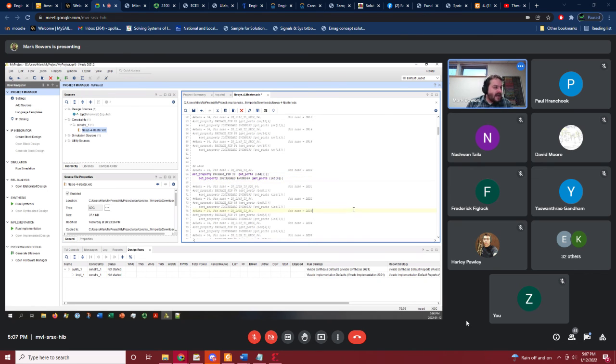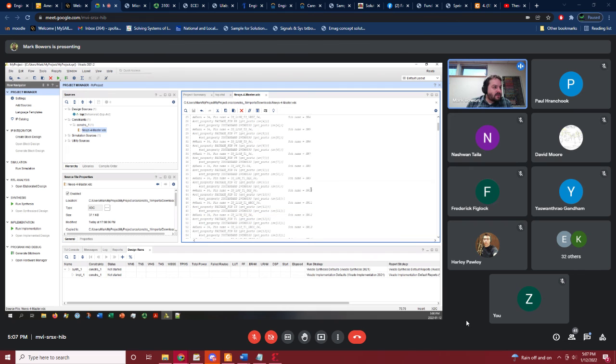Here's switch 0, which I uncommented. This says SW0 goes to a package pin, which refers to the pin on the actual package of the FPGA. It's called U6. The IO standard says what kind of voltage that pin is at. You don't have to mess with these, just uncomment them, and it'll use it in your design.